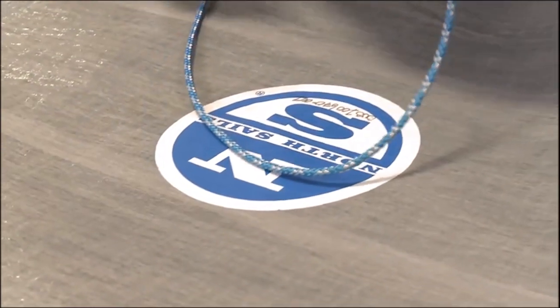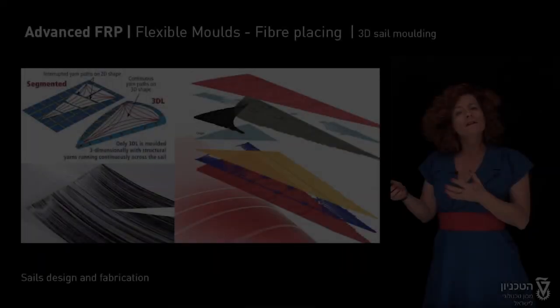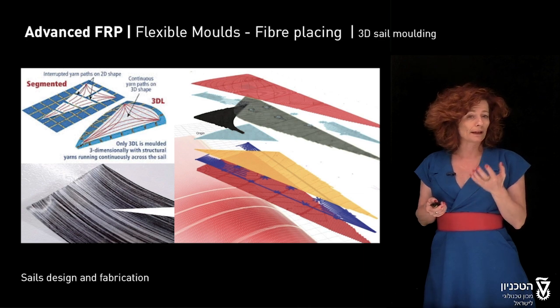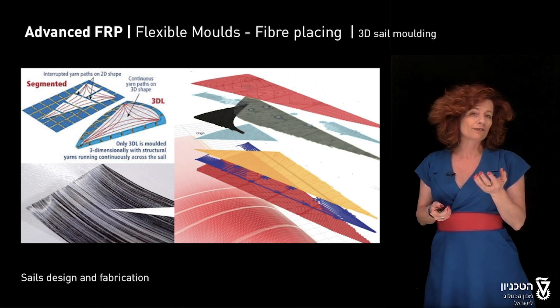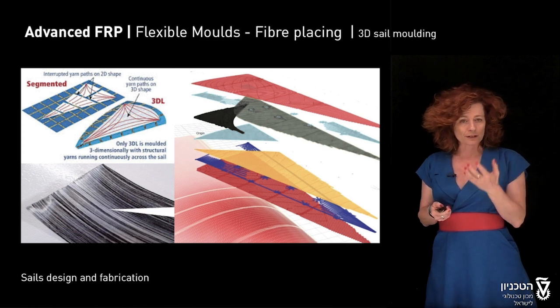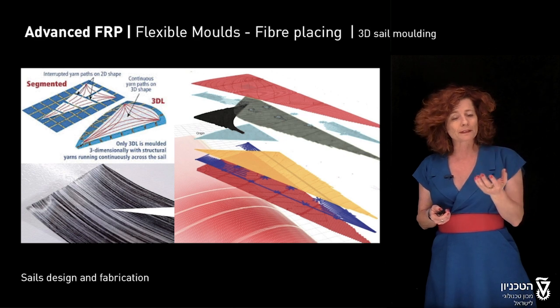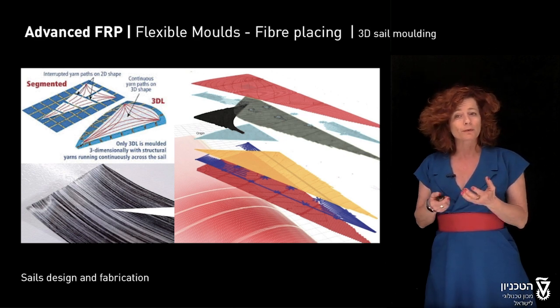The last job for us today is a thorough inspection, and Jeff explains the next part of the journey for these sails. So in the case of these sails, the stress analysis of the shape is actually what leads the design of the element. So you have the stress pattern of the sail under performance, and you adapt your material composition and fiber layout to this required performance.